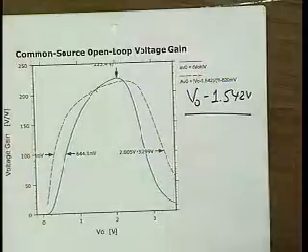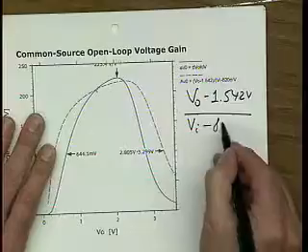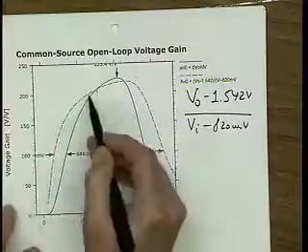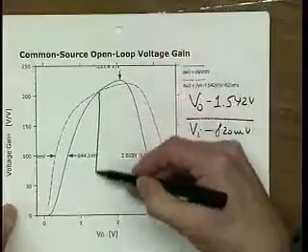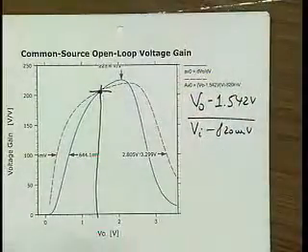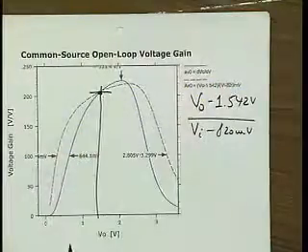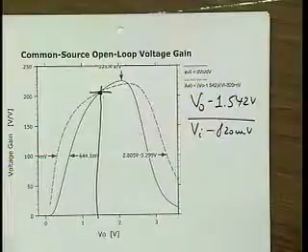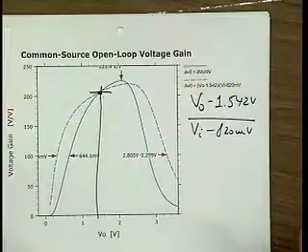It's just that for that particular circuit, over Vi minus 820 millivolts, and then this is now the bias point where they coincide, somewhere here. And then indeed at the bias point I get agreement between small signal and large signal gain, and elsewhere they don't quite agree.